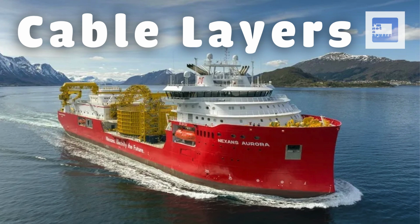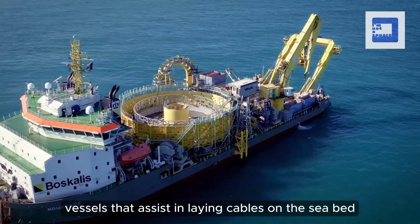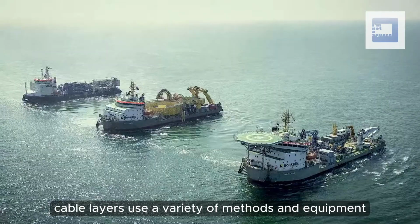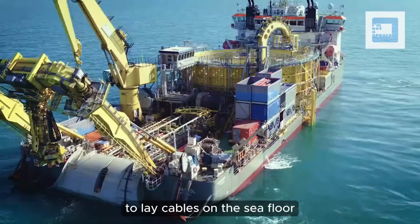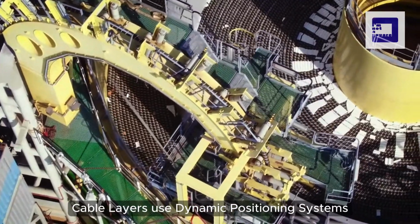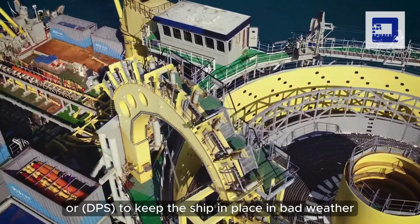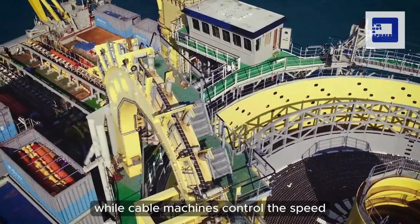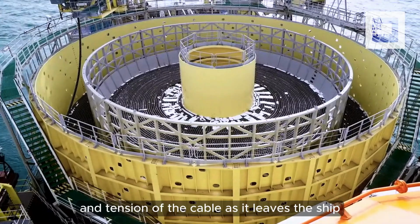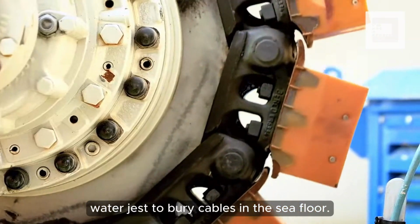Cable layers. Cable layers are vessels that assist in laying cables on the seabed. Cable layers use a variety of methods and equipment to lay cables on the seafloor for communication and power transmission. Cable layers use dynamic positioning systems, or DPS, to keep the ship in place in bad weather, while cable machines control the speed and tension of the cable as it leaves the ship, and plow devices use high pressure water jets to bury cables in the seafloor.